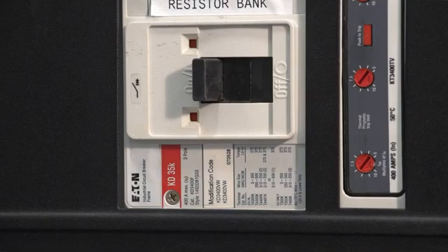As an example, a 3200 amp frame breaker may have a 2500 amp rating plug, making the breaker effectively a 2500 amp breaker. The short circuit rating is the maximum allowable fault current that the breaker can handle without being damaged. If the KA rating is exceeded, the breaker may not function properly or may fail to clear the fault current. As an example, some miniature breakers may be rated 10 KA, MCCBs might be rated 35 KA, 65 KA or more, and some power circuit breakers are 100 KA or more.